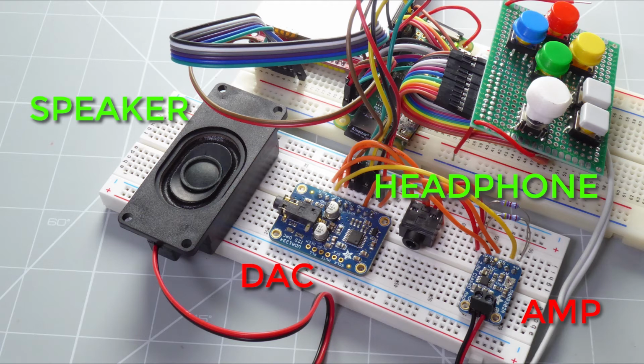The module itself actually does have a headphone socket built into it, but it doesn't quite work the way that we want it to. We want to be able to plug in headphones and have our speaker turn off, and then unplug our headphones and have our speaker turn on. So we need a separate headphone socket to provide that functionality for us, and that's what you can see the output from the DAC being fed into.